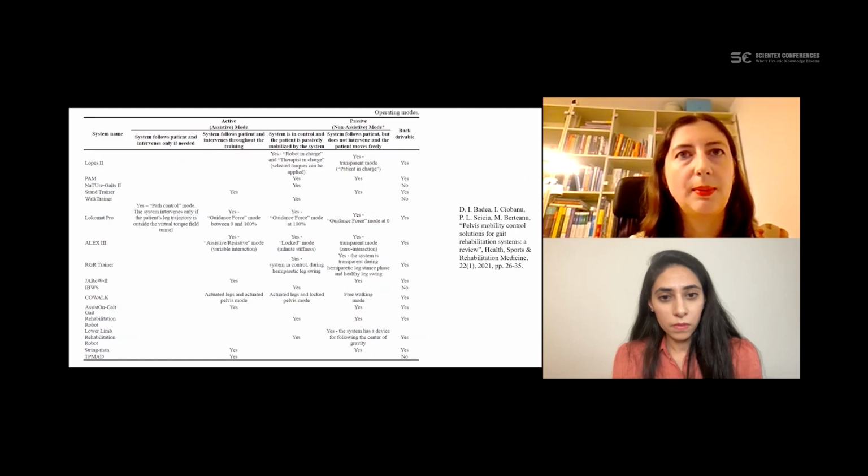In the early stages of rehabilitation, the patient is unable to move part or all of the lower limb segments. Therefore, the system should be able to make the movements for the patient. However, after a period of time, the patient might start recovering motor control, and the system must be able to adapt and actively assist the patient. This means the patient should start the movement and the system should adjust the trajectory and control the range of motion. Back drivability is used to control the force applied by the system on its user, without using force sensors and implementing a feedback loop.